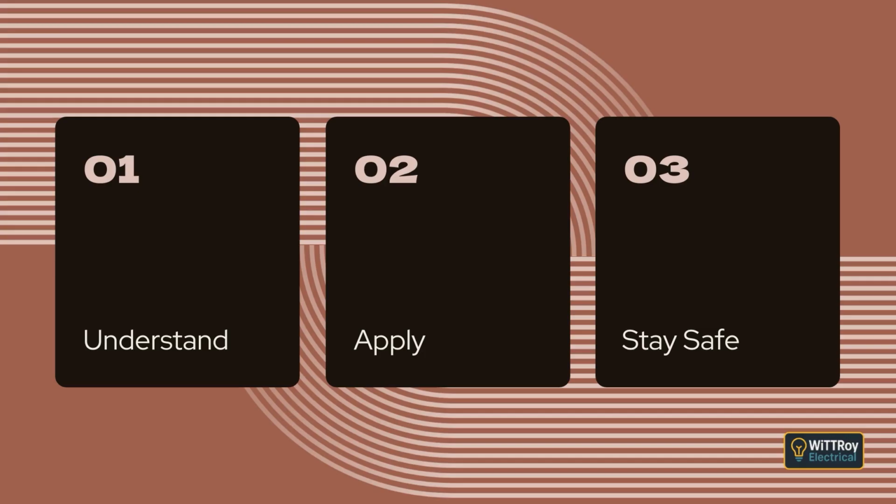Clause 2.3.6.1 General. This clause explains the general rule. A safe means of disconnecting electrical supply must be available whenever mechanical maintenance is carried out on electrically powered equipment. Many machines, like cranes, elevators, conveyors, or pumps, need clear isolation because mechanical hazards may continue even after electrical power is removed. For this reason, the means of shutting down must be secure, reliable, and capable of being locked or secured in the open position if required.